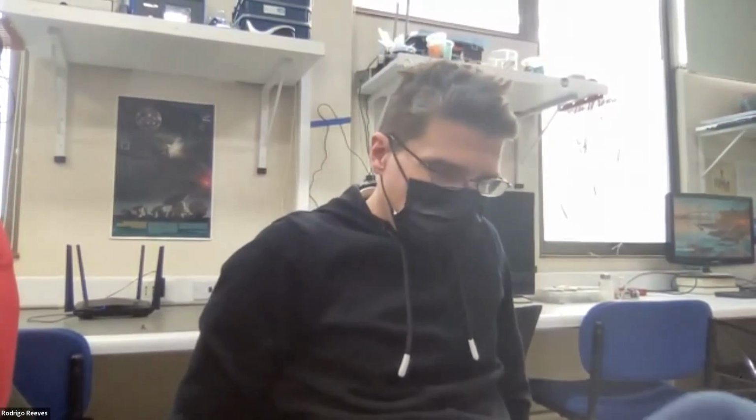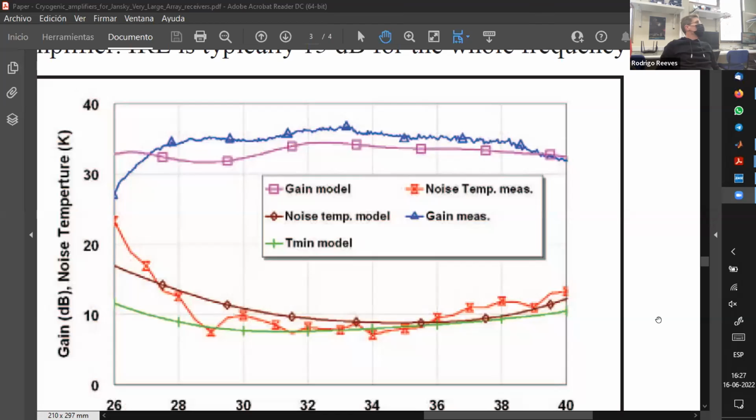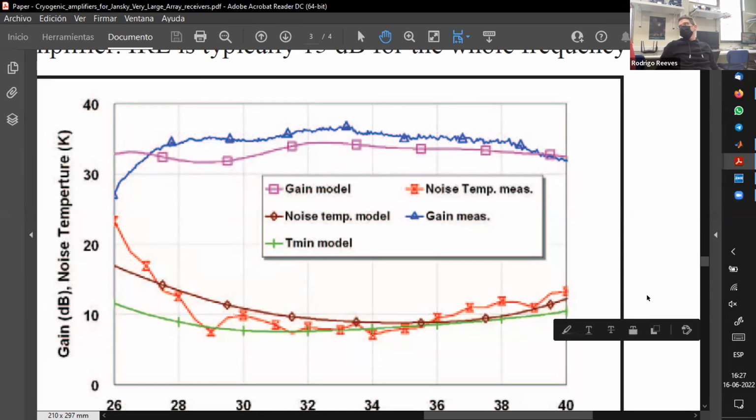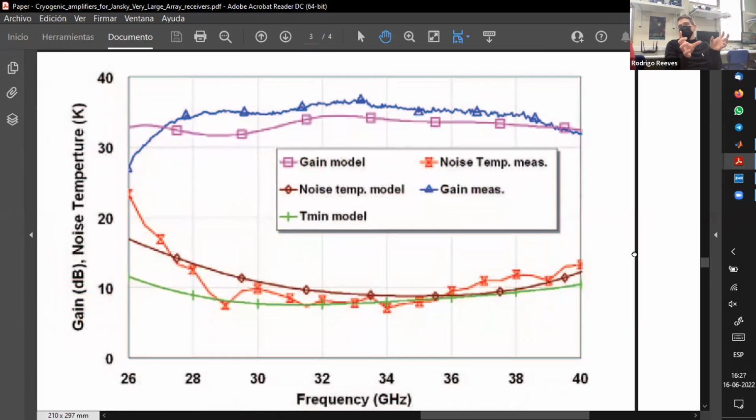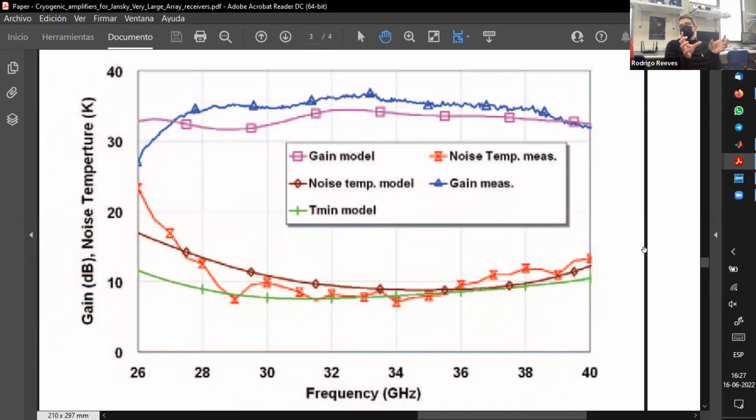So one thing is that we are having a two-stage design. I think it has to be at least a four-stage design to have the gain that they are having. But actually, if you add one more stage there, you have more freedom to play with the matching between the stages, right? So it could be even easier to get it flatter. Adding more and more, there's a limit. If you have very many stages, there's this Bode-Fano rule that you get more gain, but it gets narrow. But it's doable. I don't see any problems.